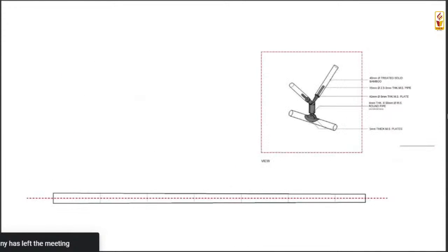So you'll find on the right above, one of the details which we are doing, where if the diameter variation is from, let's say, 7 to 12 centimeters, what should that customized saddle be, and how long should it be, so that it is able to cater to the variation in diameter. So we are trying to standardize the detail as far as possible.